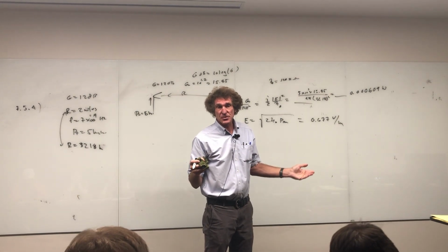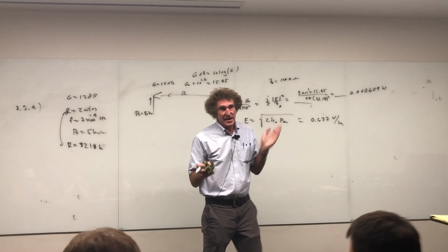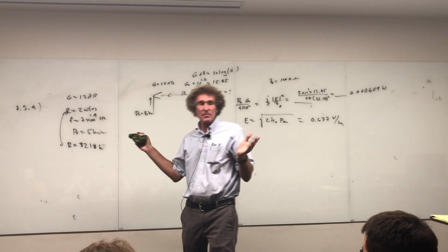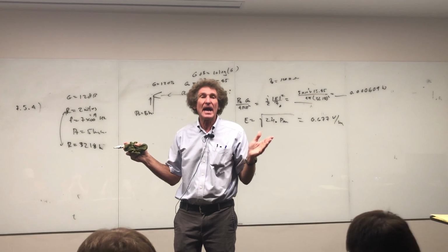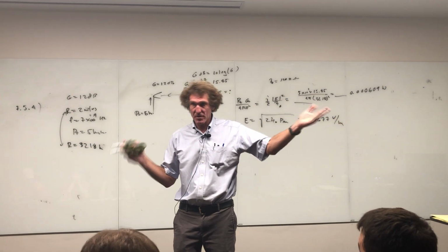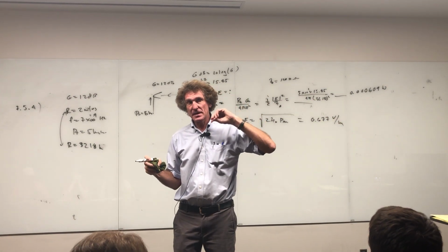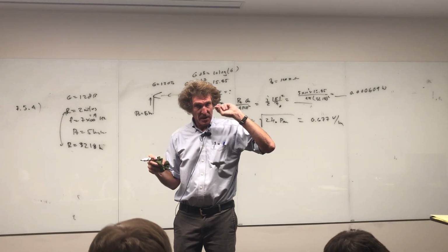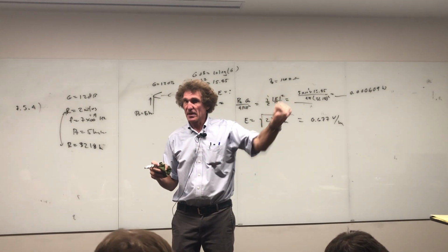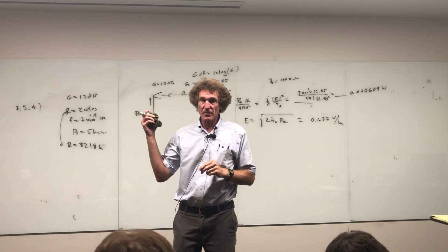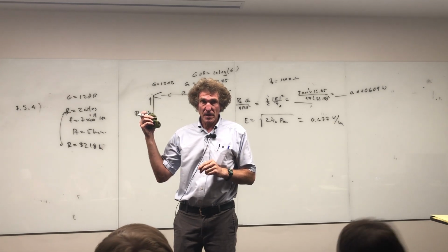These are good problems. They're straightforward. There's nothing tricky. Again, the mile conversion to meters is something you have to be adept at, and I would not ask you that without providing some conversion for you. And the second thing is make sure that for gain in dB, you use linear gain in these equations. Don't put 12 in there. That's a common mistake. Okay?